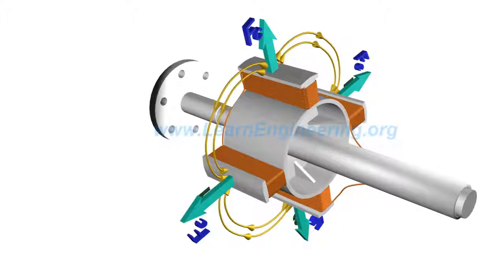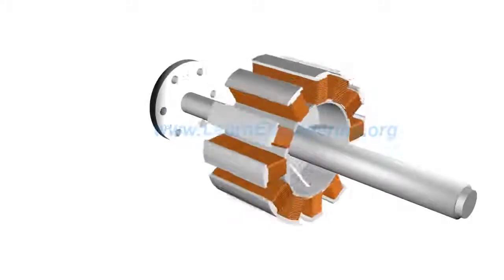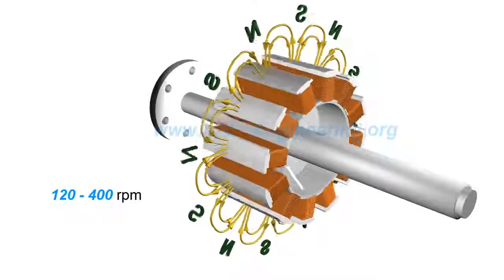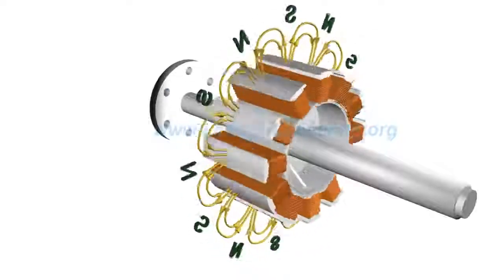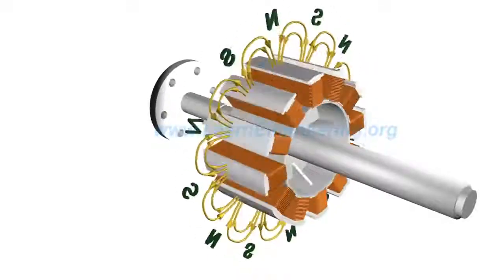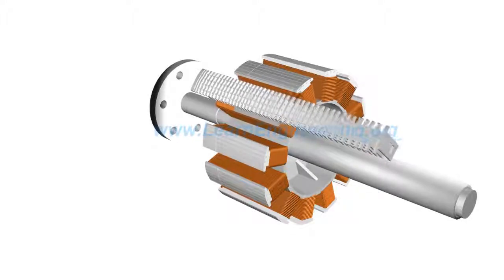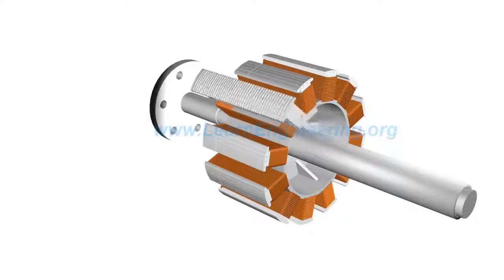So salient pole rotors generally have 10 to 20 poles, which demands lower RPM. Or rather, salient pole rotors are used when the prime mover rotates at relatively lower RPM. The pole core is used to effectively transfer magnetic flux, and is made with fairly thick steel lamina. Such insulated lamina reduces energy loss due to eddy current formation.